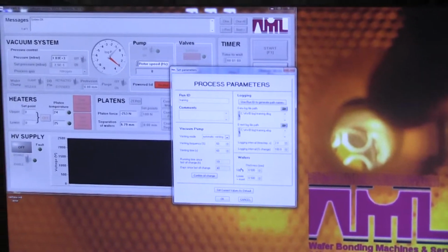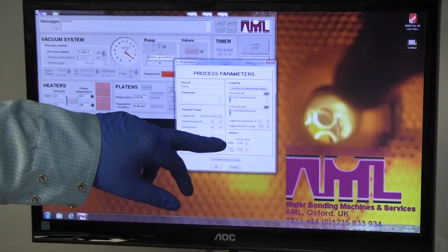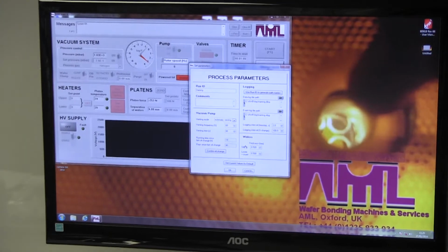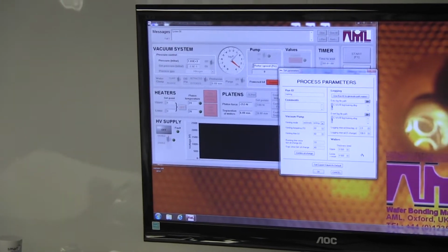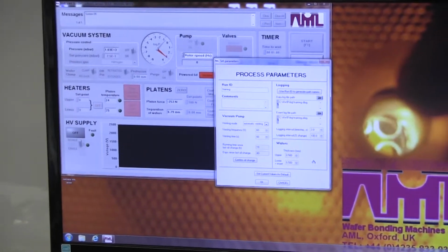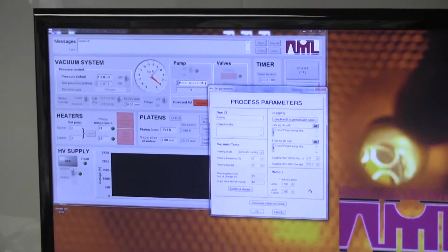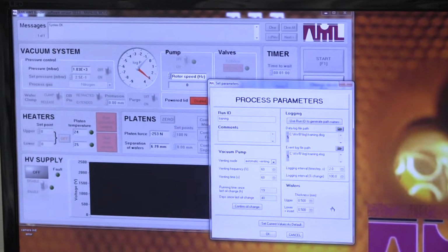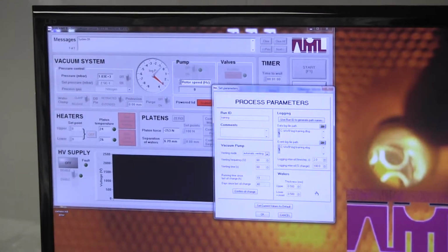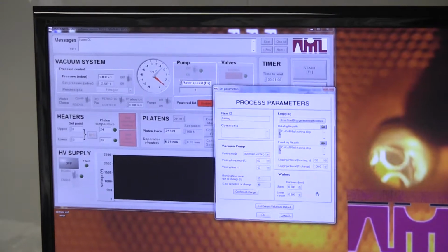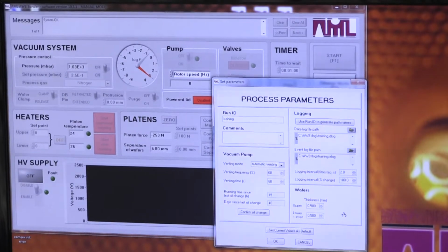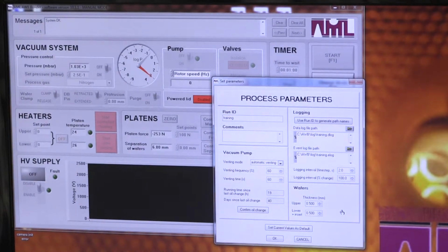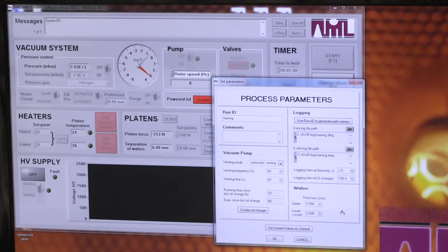Okay. The last 2 parameters, wafer thicknesses of the upper and lower wafer. These are important. Do you know what thickness your wafers are? Yes, 1 millimeter and 500 micron, or 500 and 500. So 1.5 or 500 micron. Okay. But is there like a maximum thickness? No, not really. The manipulator can separate by 30 millimeters, so if your stack is less than 30 millimeters, it will fit.